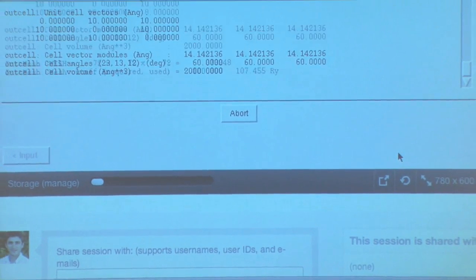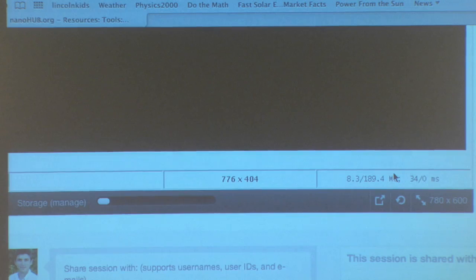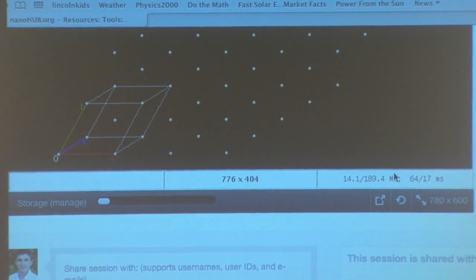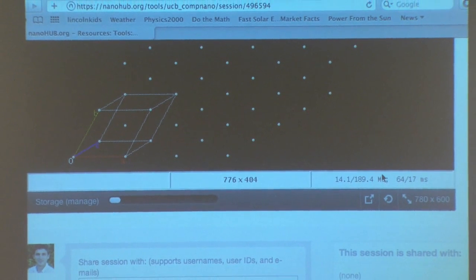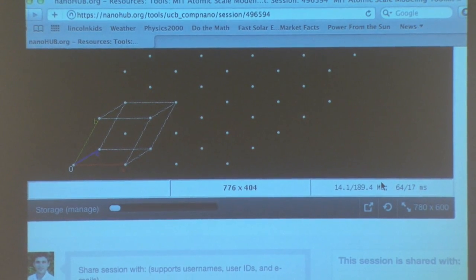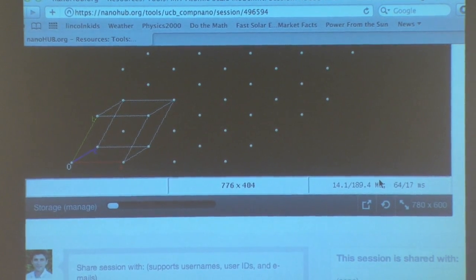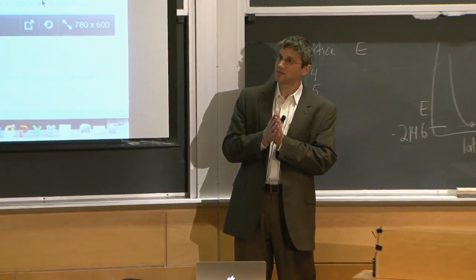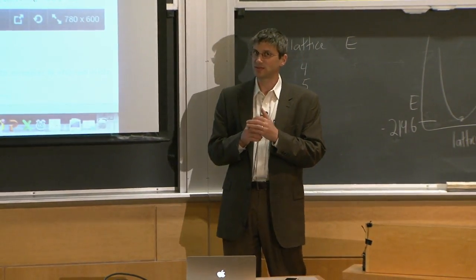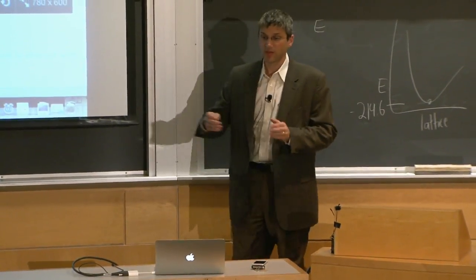Is there a way to tell after looking at the simulation if I actually should have had more K points? If I choose 1 K point, and if the band structure is wiggly, I should try to converge the K points, because it means there's a dependence on K. And if that's true, then I shouldn't be settling for not testing the convergence, right? I should at least try to increase the number of K points to see if my answer changes.